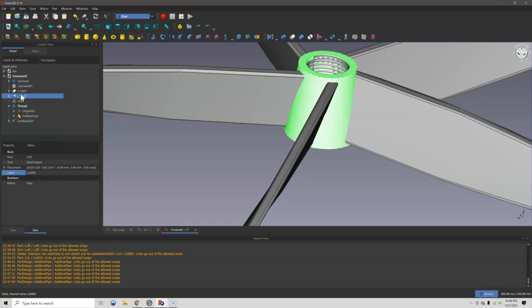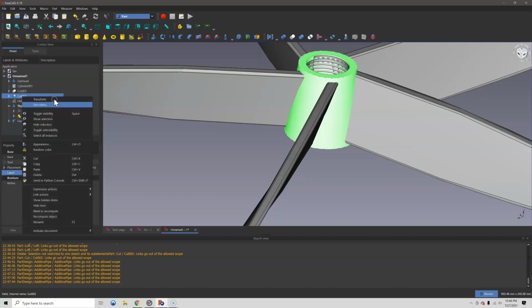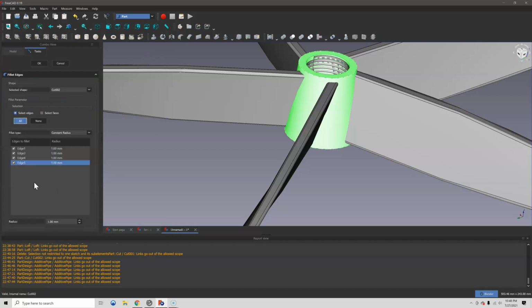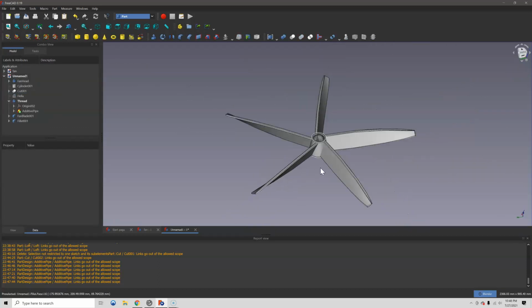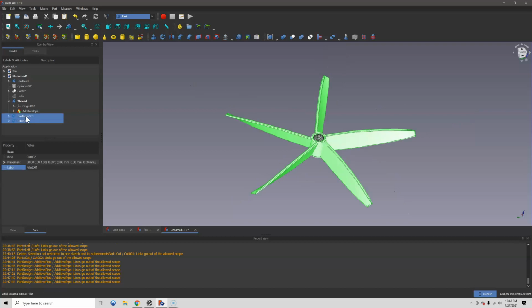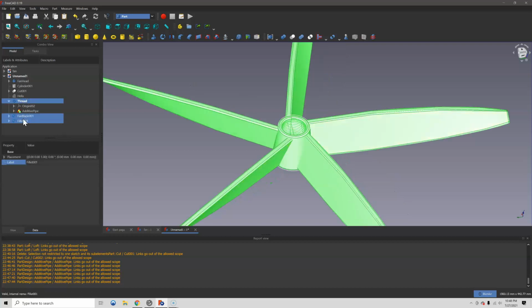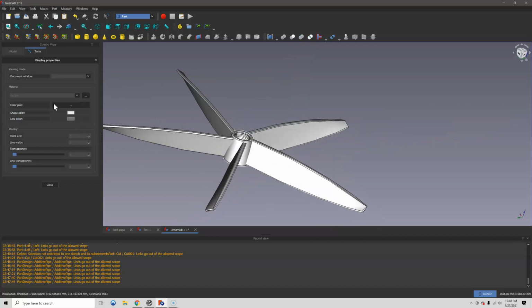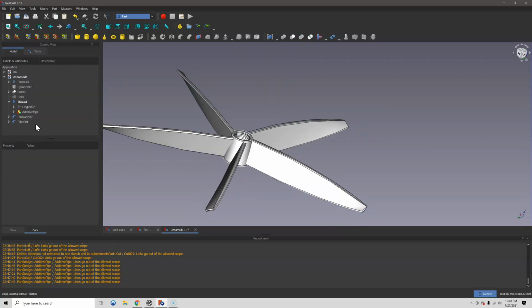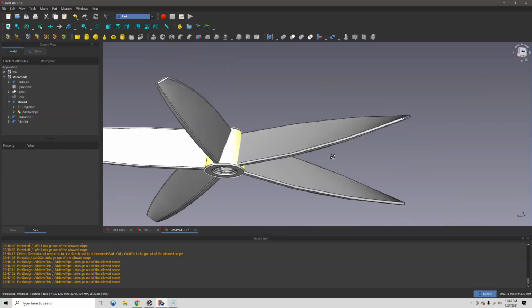And then with the head, we'll do the same thing. We will click on it, go there, select all, and do the same radius at 3. And there you go. You got yourself a fan. And this is just for presentation purposes, but you can go to appearance. Let's change it to maybe gold, like in the demo, or we can set it as chrome. We can also set it in any color you want, but that's basically it.